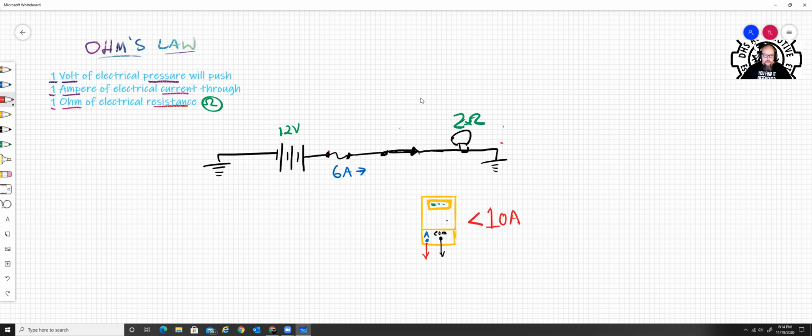So here, we're gonna make an amperage measurement. Now, if I wanna measure the flow of something, I have to get in the flow to measure it, okay? So let's just go ahead and do it at the bulb just because it's an easy area right here. I'm going to go ahead and disconnect my bulb. Okay. Then what I'm going to do, get my ammeter going here.